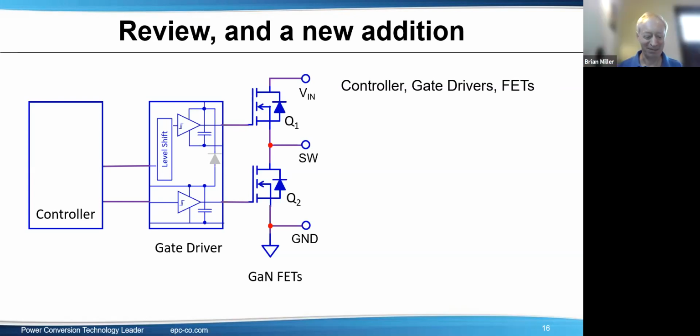Is it possible to calculate the rise and fall time with different load capacitances? I think I assume they mean on the gate driver. I'm not totally sure what the question means, so I can answer two ways. One is I've noticed a lot of gate drivers specify, especially MOSFET ones, very high capacitance loads. And when you use these kinds of gate drivers to drive a GaN FET, you get speeds that far exceed what the data sheet for the MOSFET gate driver says it'll do, because the capacitive load is so much less.